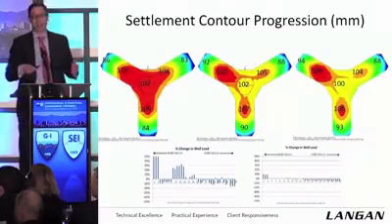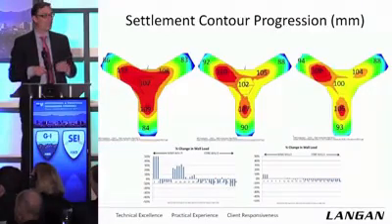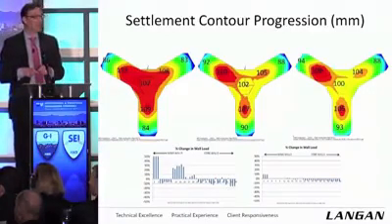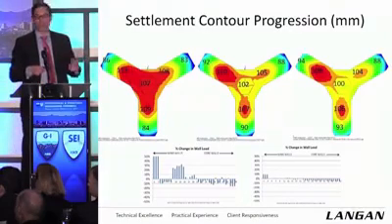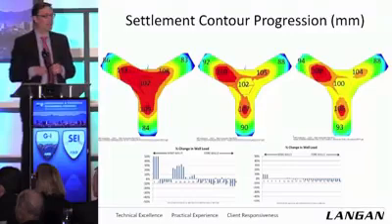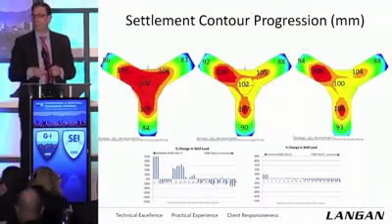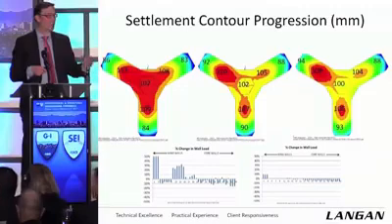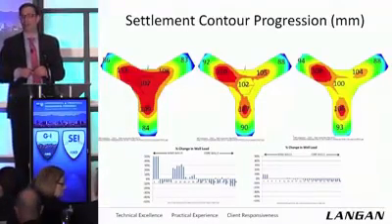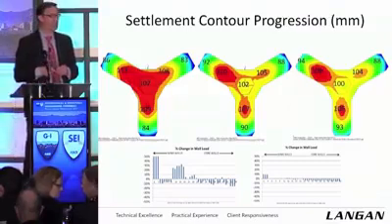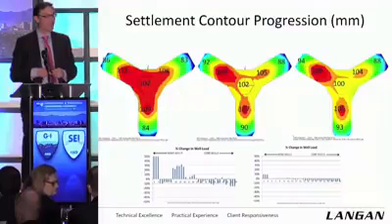So now things start looking a lot better. On the left is our first cut again. That's the first wall loads takedown. And instead of 175 at the middle, we've got 107. In the first iteration, the wall loads did still move around some. We had about 50% increase on the end walls, but not nearly as bad as the first cut. And then in our second iteration, the wall loads were essentially all less than 10%, and most of the time less than 5% change. So we felt like, all right, we've got it now.